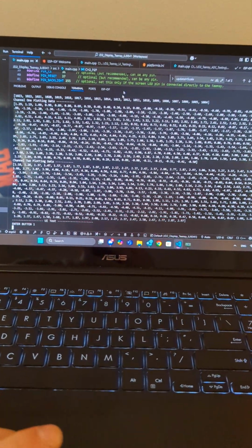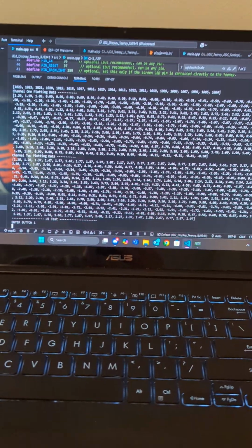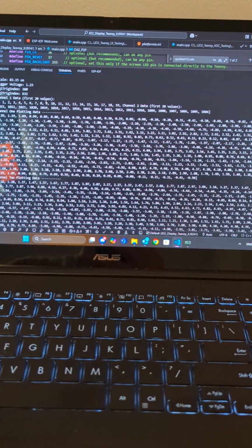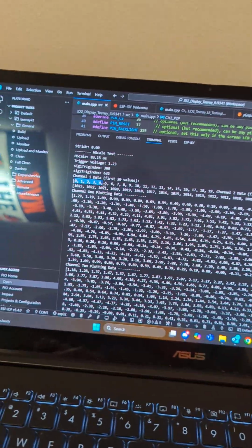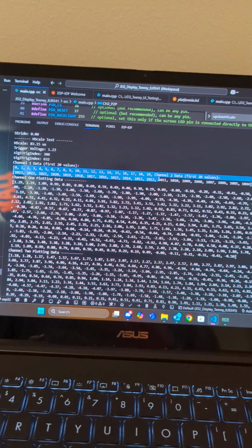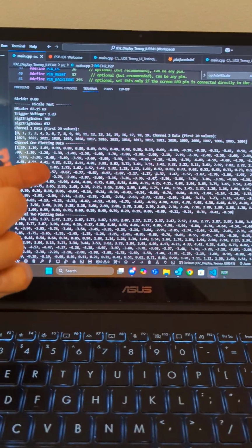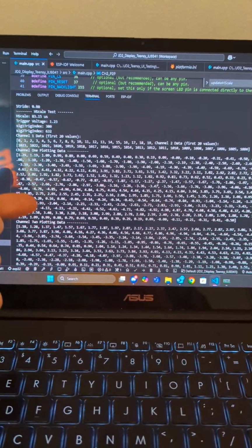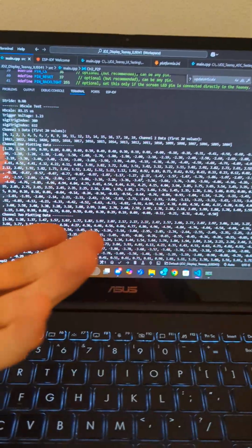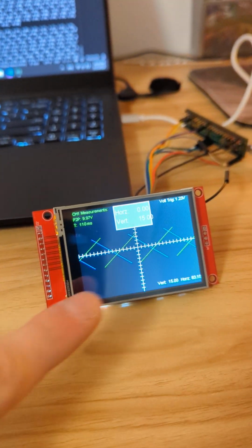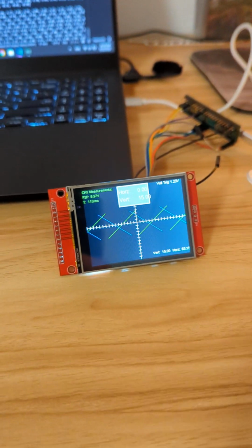And then this is sort of hard to show on video here, but this is just all the data points, and at least for my interface validation where I'm taking in 4,000 data points and plotting out 320, here's the first 20 values of my 2 channels of 4,000, and then this is being converted into voltage data, and then I'm selecting 320 points depending on the stride, indexing the array, which is based on the horizontal scale. These are my 320 points that corresponds to 320 pixels across. So those are the 320 points that I'm doing.